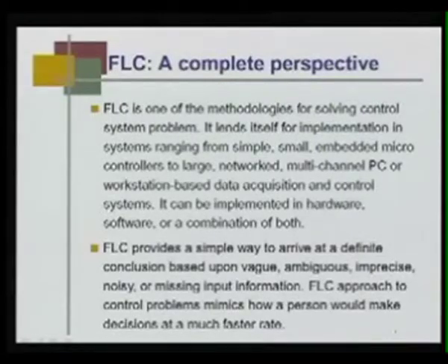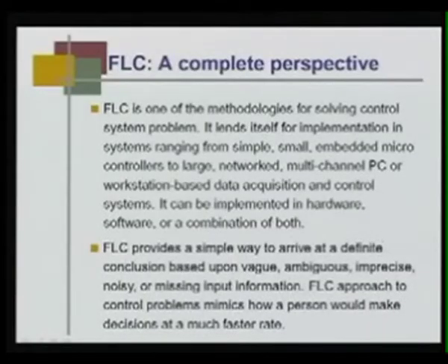Fuzzy logic control is one of the methodologies for solving control system problems. It lends itself to implementation in systems ranging from simple small embedded microcontrollers to large networked multi-channel PC or workstation based data acquisition and control systems. It can be implemented in hardware, software or a combination of both. Fuzzy control can also be implemented directly in fuzzy hardware, fuzzy chips. A fuzzy logic controller provides a simple way to arrive at a definite conclusion based upon vague, ambiguous, imprecise, noisy or missing input information.